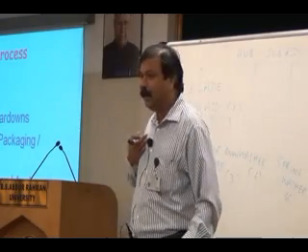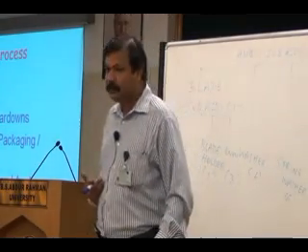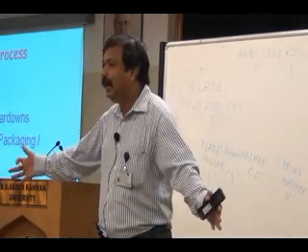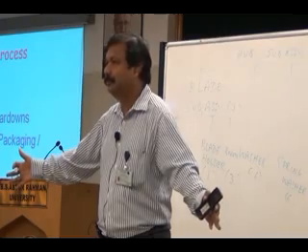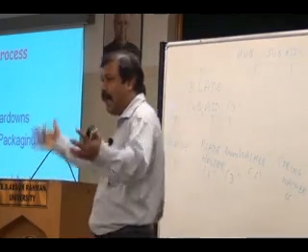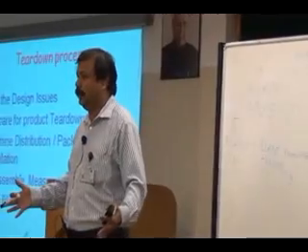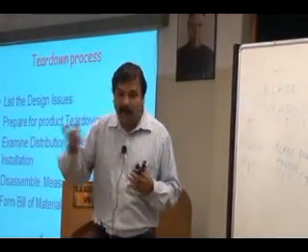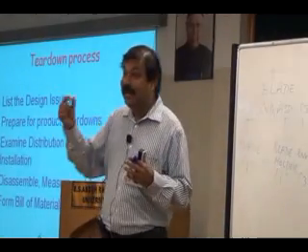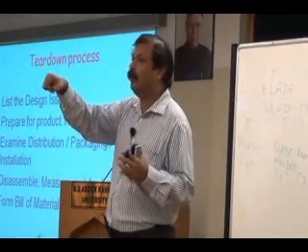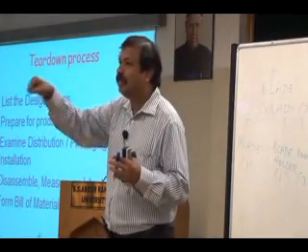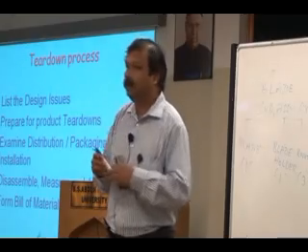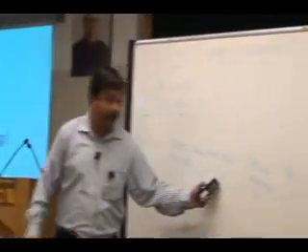The load, I don't have any control over because it is coming onto me. But what I can do is have a large area over which this load is distributed, so that stress is minimum. So the washer does the job. It doesn't let the load be concentrated at a few points. If the load is concentrated at a few points, then it may damage those local points. So the washer is an essential mechanical component.